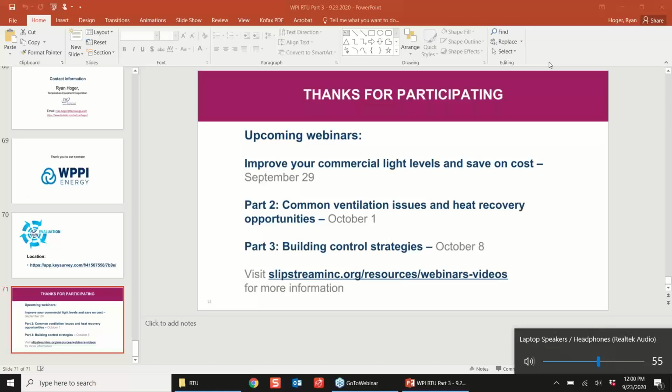So if you have noise problems, that's one of the very common things you go look at and think, oh, whoever installed this 4 years ago never took my shipping bolt out. Dang it. So that's something to point out.